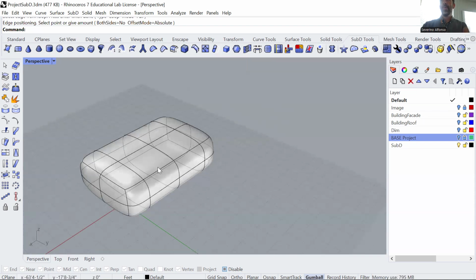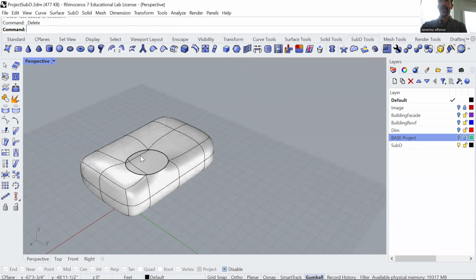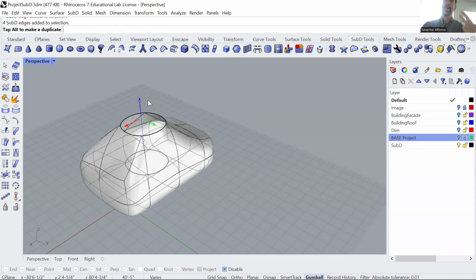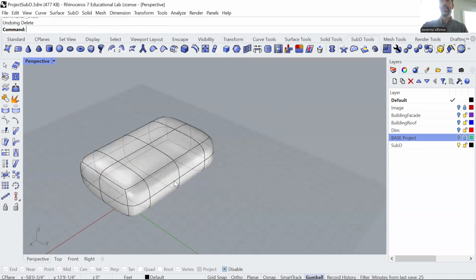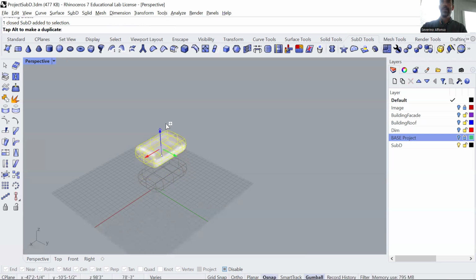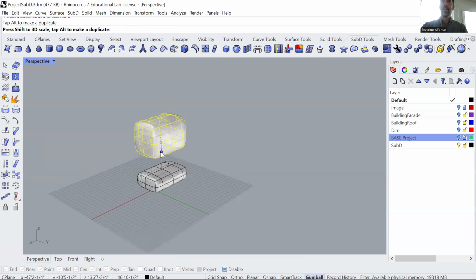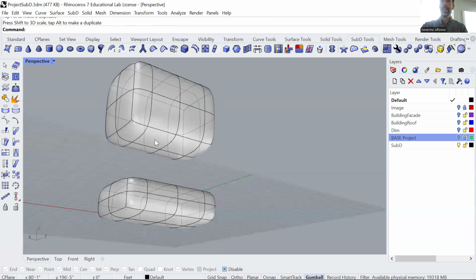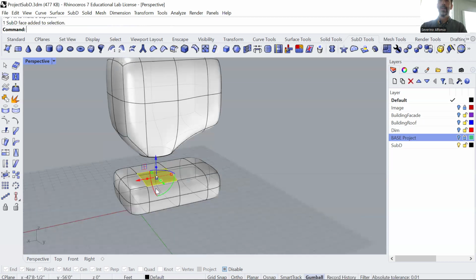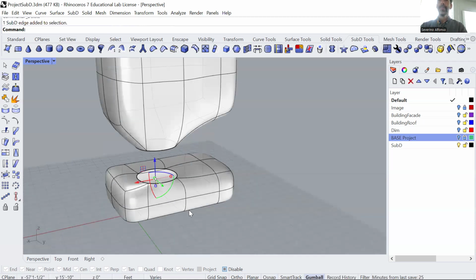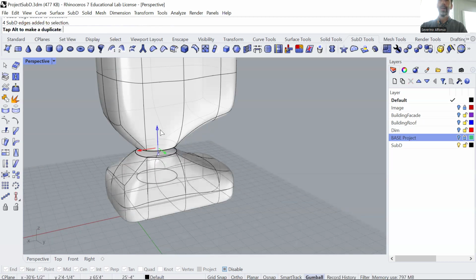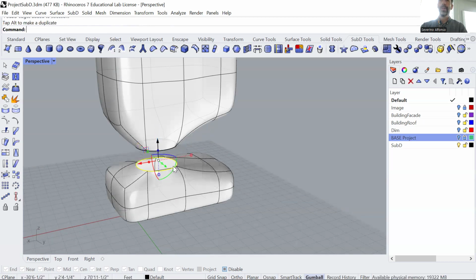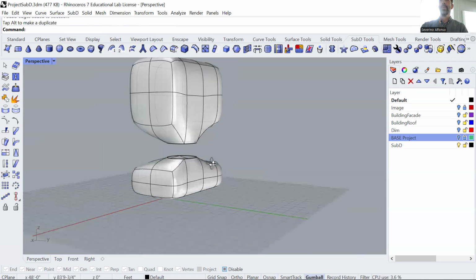There's a couple more important tools which you can use. When you delete one of the faces, you can also Control-Shift and select the ring that is open, so it creates that kind of a boundary. So one thing you can do, I'm going back, is copying one of those elements and deleting the face from here, Control-Shift to select and take it down, and use the same face here, and Control-Shift the ring of that to take it up. Now, I can't really connect those two, but there's a very useful tool that we can use.